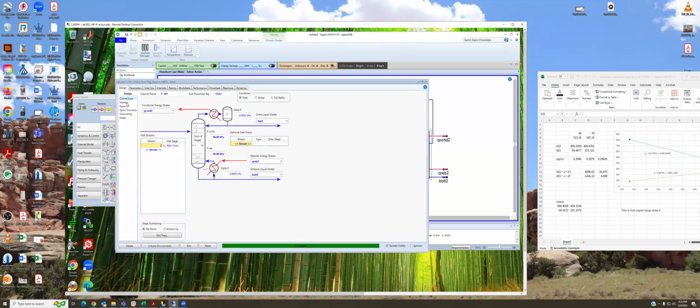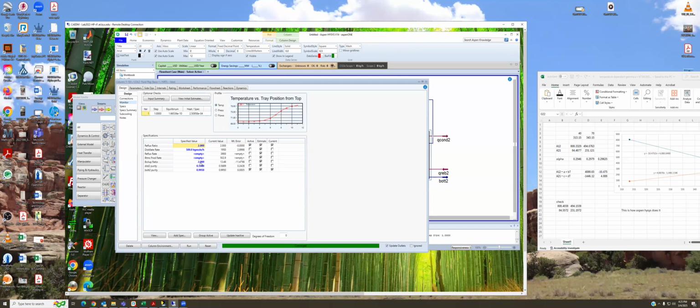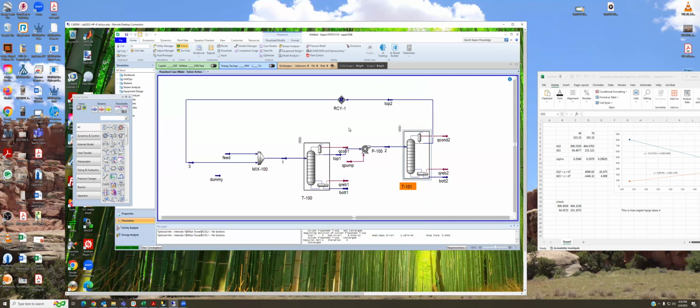Okay, so now that column is operating with good specifications. So let's do the same with the second column. Boil-up ratio is 15.48. We use that. And again, everything stays converged. We've still got the purities we want, but now we're operational. Okay, there you have it. Process to separate ethanol and ethyl acetate. And even though we had a minimum boiling azeotrope with two columns, we can accomplish this separation and have pure product streams.